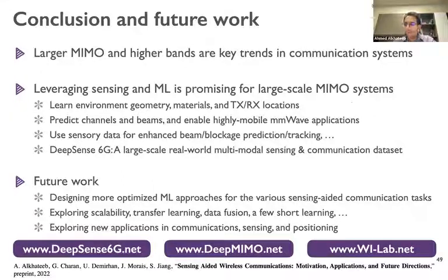The other side of the story is that if your question is about predicting CSI, then in my opinion it might not be very practical in general to use machine learning models to predict the final CSI. Especially in large scale MIMO systems, where machine learning is probably more interesting, the channel becomes very sensitive to little imperfections in the estimation. So the approach I believe is more practical is a hybrid solution, where you rely on machine learning to reduce the dimensionality of the channel estimation problem, and then use over-the-air classical refinement to estimate the channel.